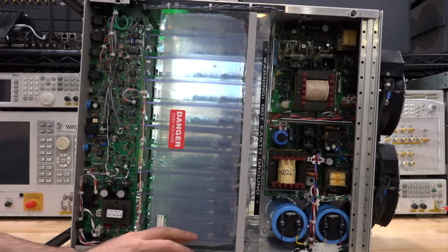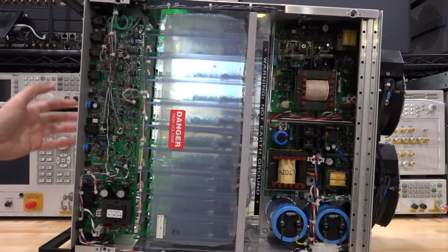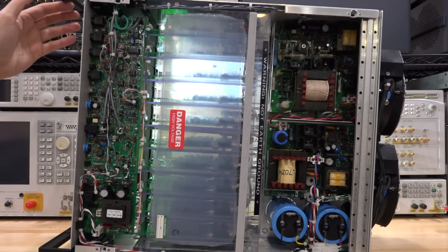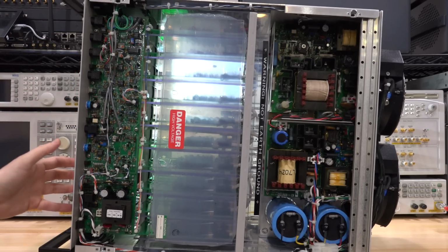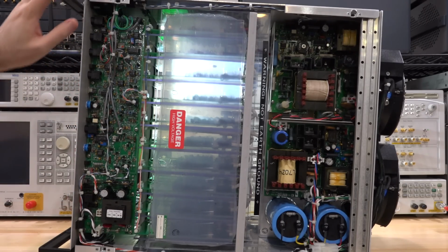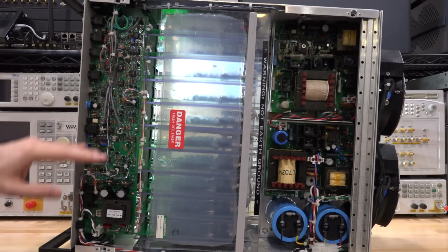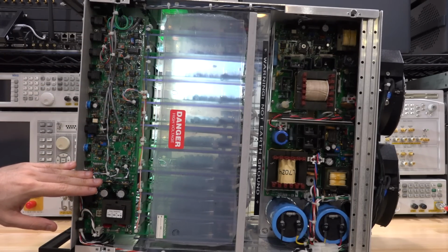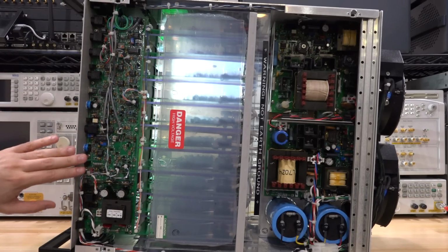Now, this instrument is made of 3 main parts. We have the front, which is where the human interface is. Except for the high voltage section, the amplifier input, the output monitor, things like trip and current limit, and interlock switches are all handled by this main board here. And this main board also drives all the subsections of that stacked amplifier stage I showed you. You can see that this wire over here, everything is in series in the positive and the negative section.